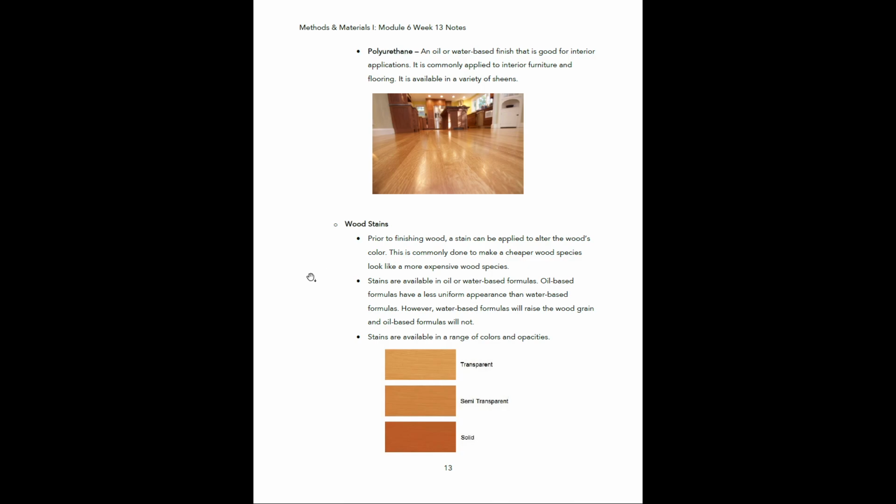Stains are available in oil or water-based formulas. Oil-based formulas have less uniform appearance than water-based formulas. However, a water-based formula will raise the wood grain and an oil-based formula will not. Okay, so that's something to consider.